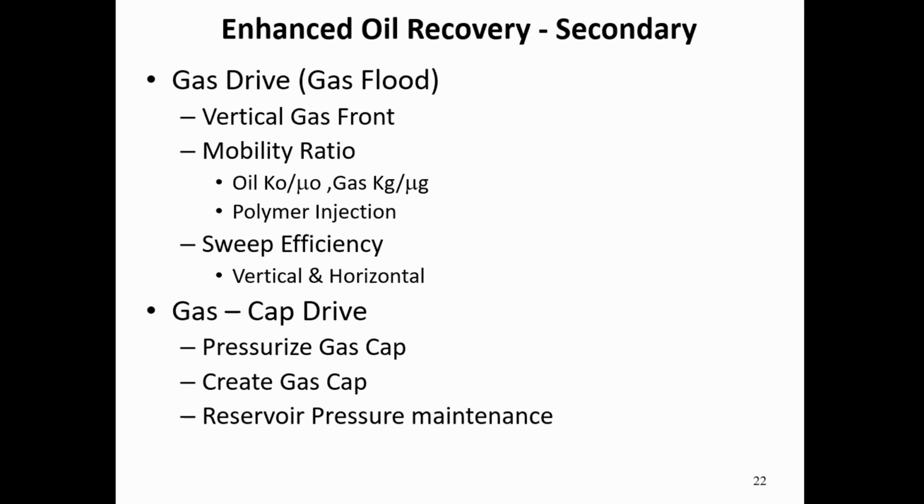But be careful as well with the chemical you add, because some chemicals can attack the rocks and cause damage to the rocks. So you have to balance. You have to do some kind of lab testing. As you know, some of you are geologists, and you know the rocks, some rocks could interact with the chemical we inject. So we need to make sure the chemical does not react with the rocks I have, such as carbonate rocks or silica rocks or salt rocks, anhydrite, and so on.